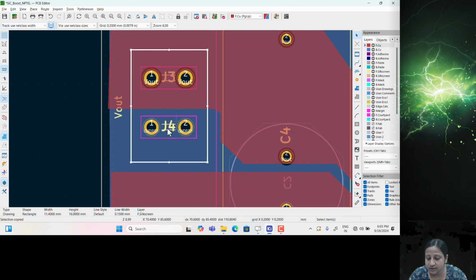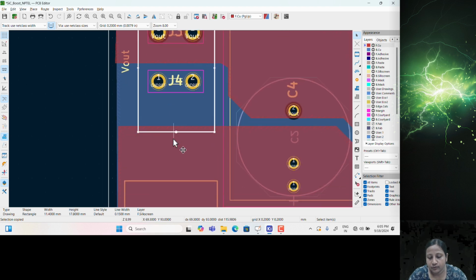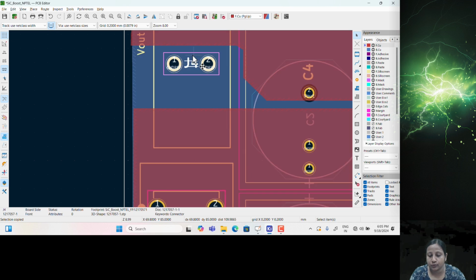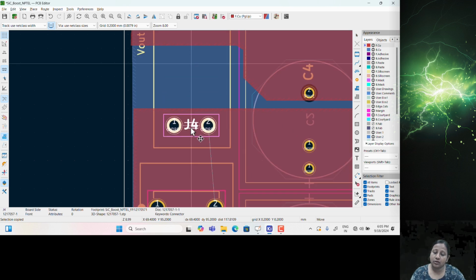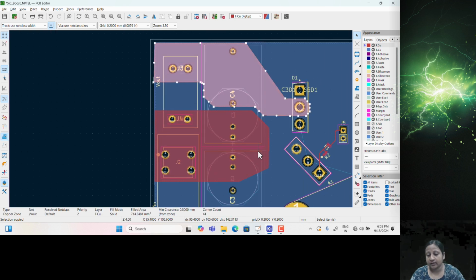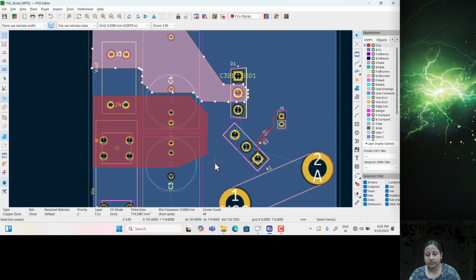So either you can connect it similar to the wire connection for different resistances, or you can put this shaded portion. For the power part it is always advisable to put the input and output, like ground and the sources, in this shaded way. It will always give you a better result.